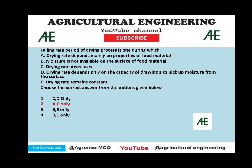So falling rate period of drying process is one during which drying rate depends mainly on properties of food material. Moisture is not available on the surface of food material. Drying rate decreases. Drying rate depends only on the capacity of drying air to pick up moisture from the surface. Drying rate remains constant. So the correct answer is falling rate period of drying process is one during which drying rate depends mainly on properties of the material and drying rate decreases.